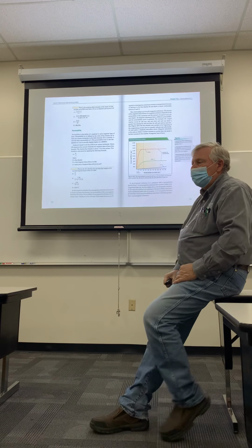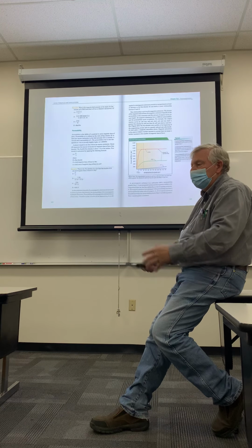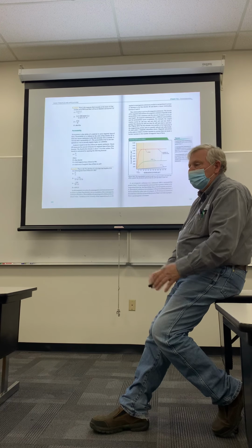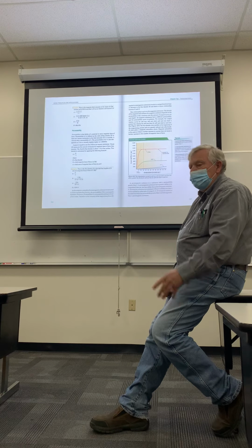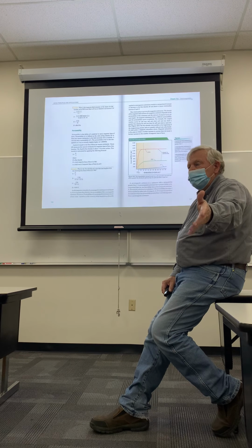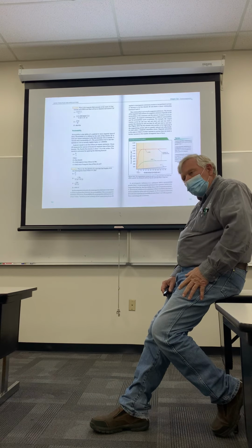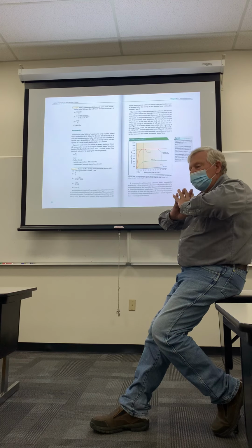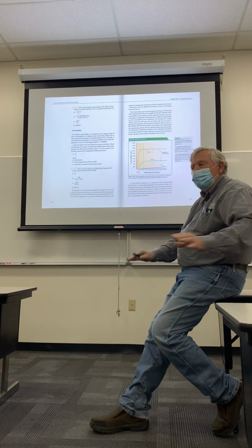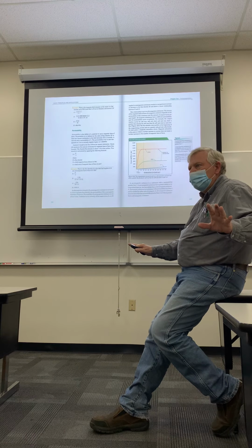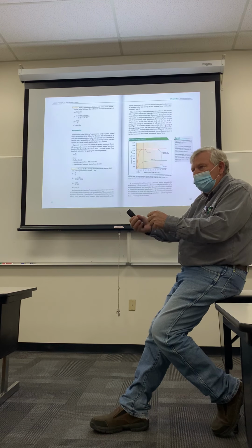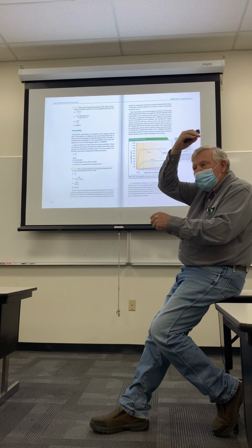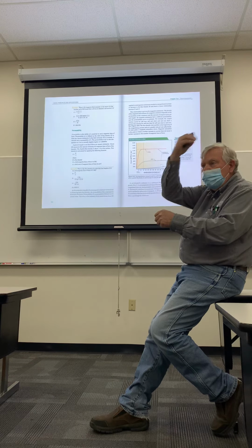And in a lot of the work that I do, quite often we'll get out on a location somewhere and the welders will be working on a location and they'll holler at me or the boss or somebody and they'll say, "We can't weld this, it's too magnetic." So you go over there and they've got a file stuck to the side of the pipe, or they've got a hammer stuck to the side of the pipe. You've got to reduce that magnetism out of that material. If you don't reduce that magnetism out of it, you can't weld it. You're trying to weld it, and the hot metal jumping from the electrode to the pipe is flying off. It's like hot sand blasting coming off.